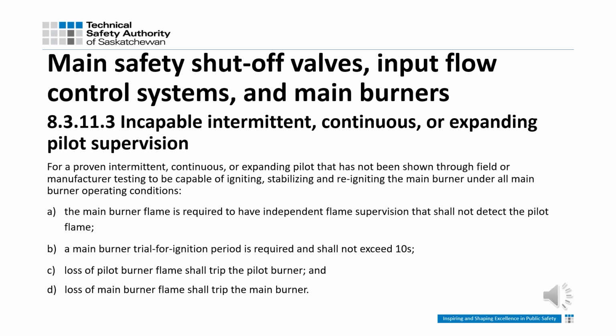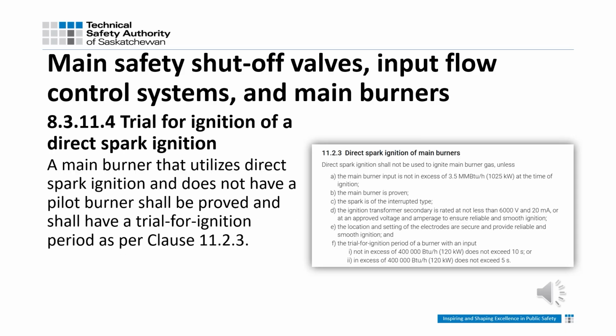8.3.11.3 gives the requirement if the pilot does not meet the requirements of 8.3.11.2. 8.3.11.4, trial for ignition with direct spark ignition, shall meet the requirements of 11.2.3, direct spark ignition of main burner.